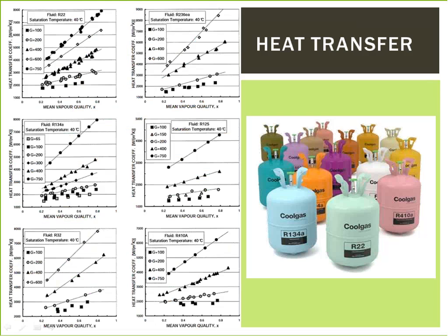The main purpose of refrigeration is to move heat from where it is not wanted to where it is wanted. Heat transfer is key to this process. It is possible for a refrigerant to have run-of-the-mill theoretical efficiency, yet be an excellent performer because of its strong heat transfer performance. Good heat transfer allows close approaches in the heat exchangers. This in turn means smaller lifts for the compressor and improved efficiency.